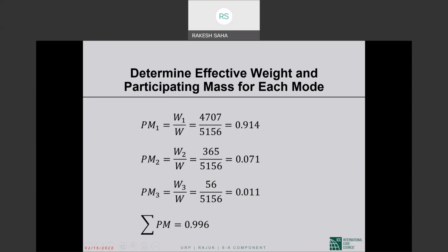So basically, this is not refined, this is kind of crude, but what this says is 91.4% of the mass of the structure is vibrating in the first mode, 7.1% in the second mode, and 1.1% in the third mode. Okay, that's basically what we are getting.